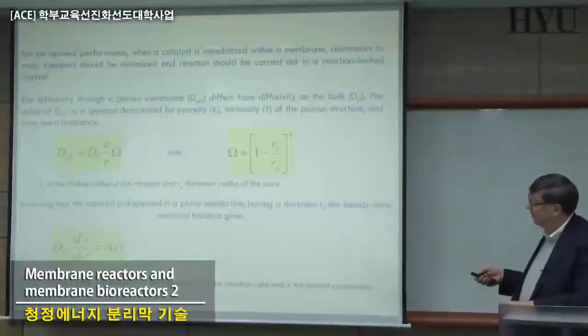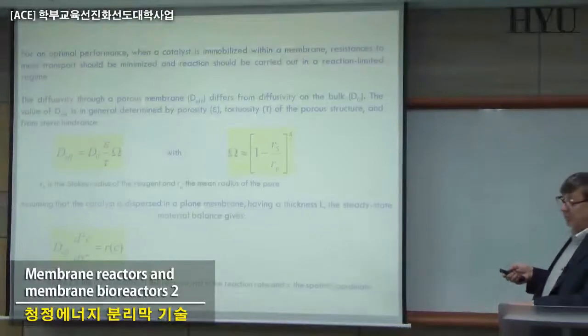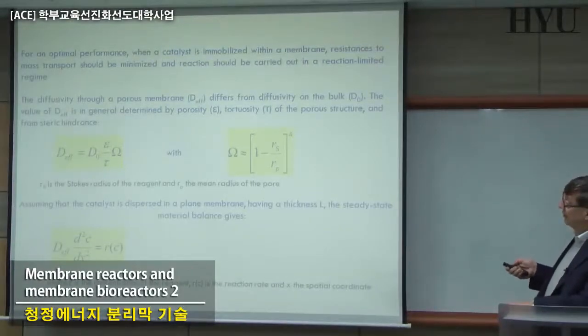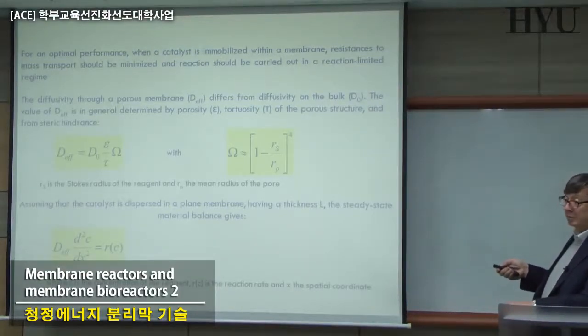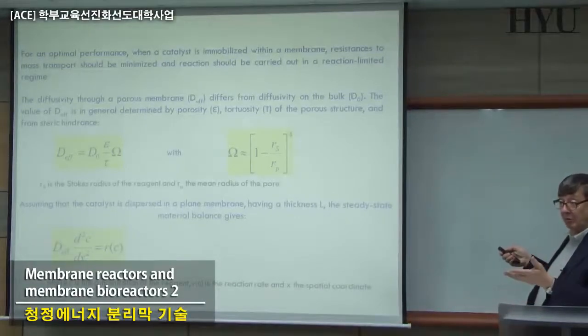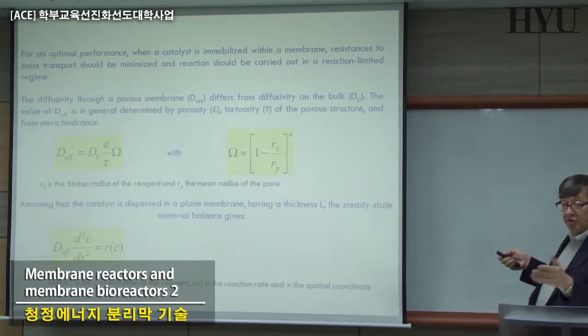The only trouble is that you have to minimize this mass transfer resistance, because the diffusion coefficients of your reactants through a porous membrane are quite different from the diffusivity of the same compound when it is free in bulk solution in a homogeneous system.